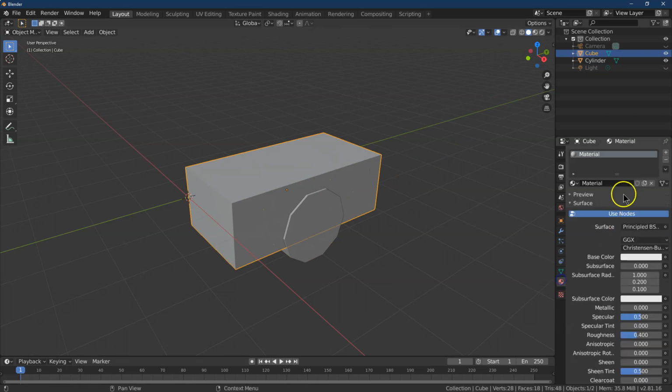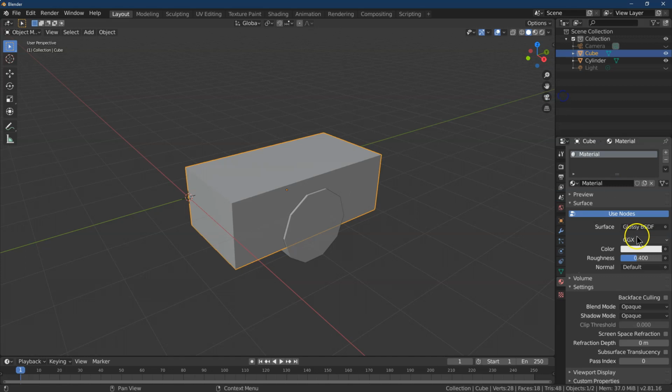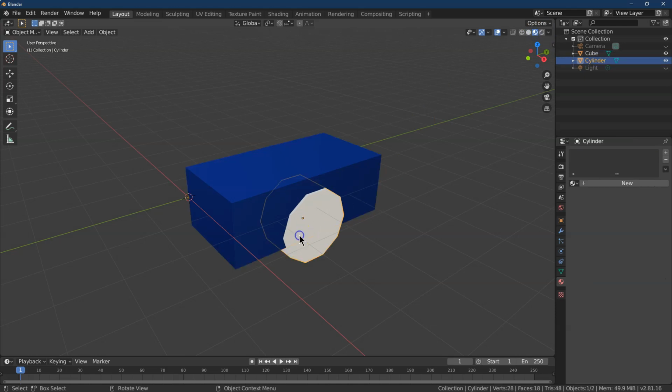So now we're going to want to have a main color for our vehicle, actually. I'm going to click on the vehicle, and I was thinking of a glossy color, a color I've really been using a lot as of late, and I think it's a good car color. Of course, use whatever you want. It's 214FC6 for the hex code here, and then maybe a 0.6 on roughness. And this is a glossy material. I'm going to call this main, and let's apply it.